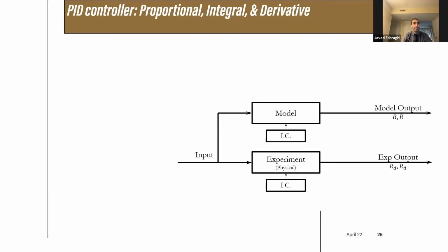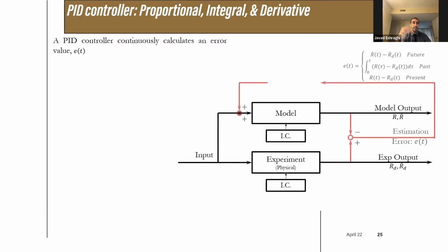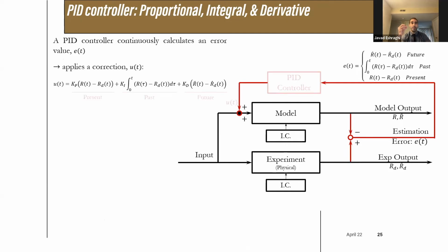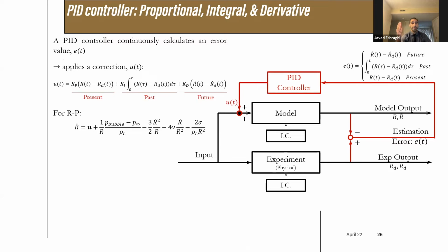This technique places an observer variable in the governing equation and uses a proportional integral derivative, which is known as PID control law, on the difference between the predicted and measured cavitation bubble diameter. In other words, when the predicted bubble diameter by the model and the experimentally measured value have a discrepancy, an error term is calculated and is fed to the PID controller. The controller then generates a source term in the original model equation and iterates until the error goes below a certain value.